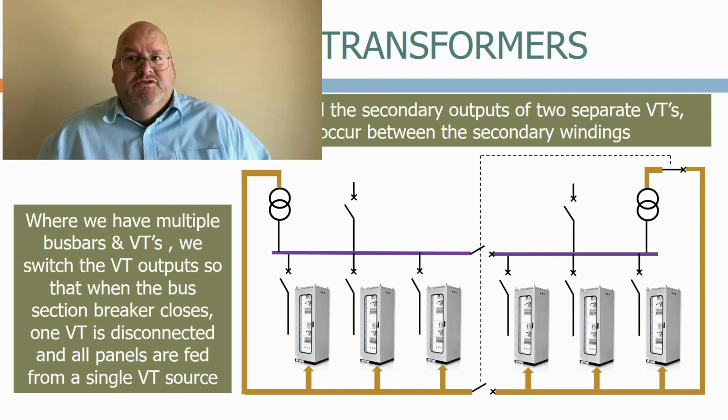Busbar VTs are used widely in distribution networks, as the protection systems tend to be quite simple, and we don't need a separate feeder voltage unless we are synchronizing between different networks. The circuits to switch the voltage supplies can become extremely complex, and can use up valuable circuit breaker auxiliary switches.